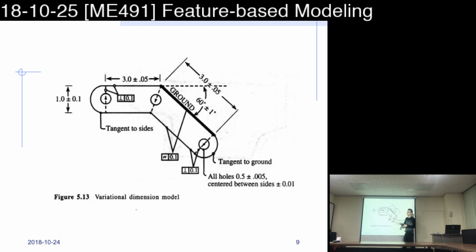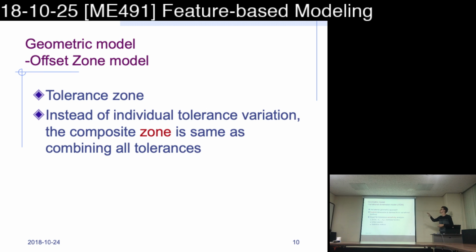In a circle around this point. So to decide where we cut it conventionally, we use the variational method, which is basically minimizing the energy approach analogy. And so integrating the tolerances in the model allows us to do some analysis with tolerances, other methods to figure out if our model works, and we can do some FEM based on tolerances, for instance.